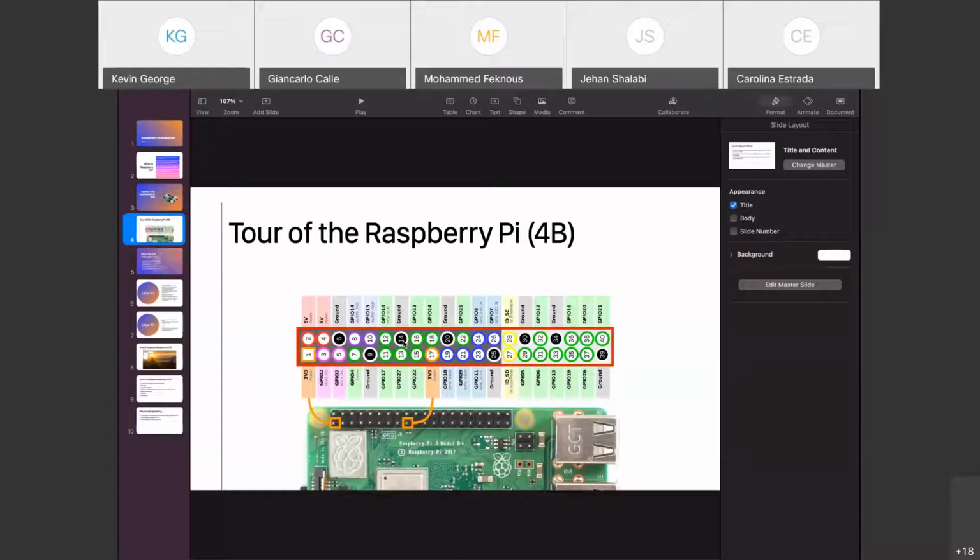If you're using a smaller breadboard, you won't have the opportunity to use rails. You're just going to have to directly plug the 5 volts and ground into the available space you can use. But if you do have a bigger breadboard, I recommend using the voltage rails because that's going to make your wiring setup much cleaner and easier.